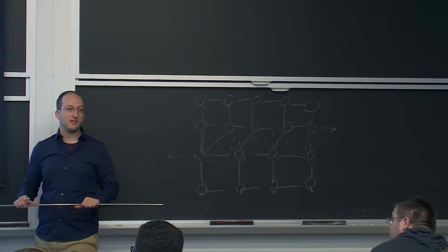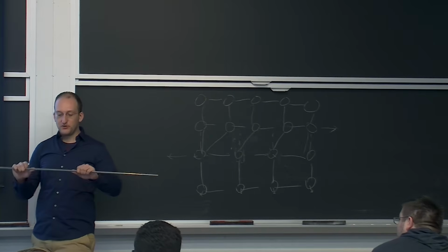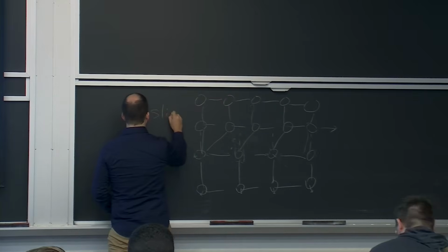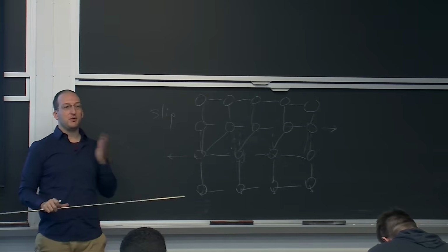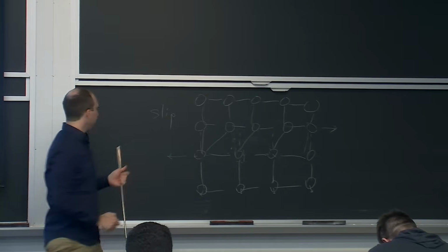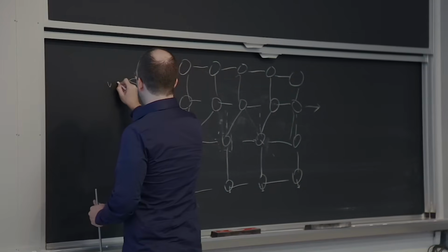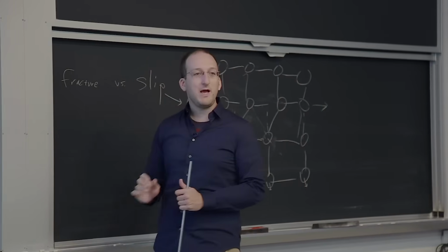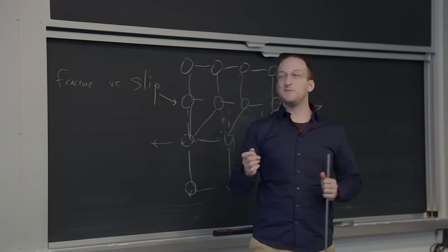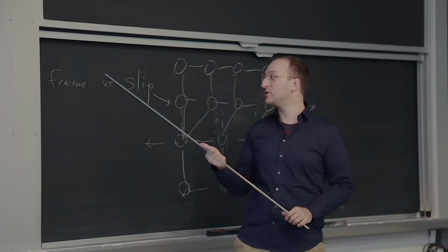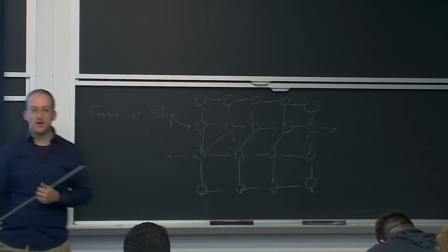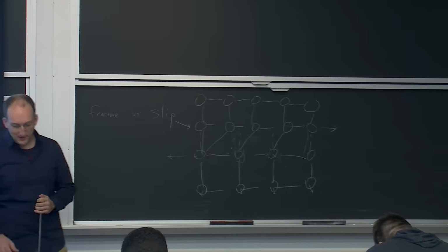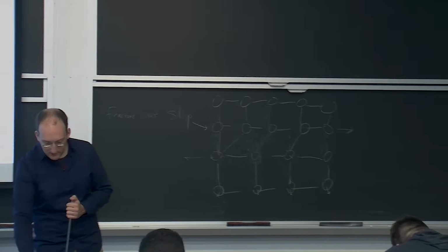Now you might ask, well, then why do things actually break? Whether or not things deform or break is a balance between this process, which we call slip, and breaking an entire plane of atoms, which we call fracture. So this one's called slip. The other mode is fracture. We would rather materials deform in systems like reactors by slip, just moving a little bit, than just breaking altogether. Unfortunately, when enough radiation hits materials, you can fracture things in a brittle manner, and we'll see what happens then.